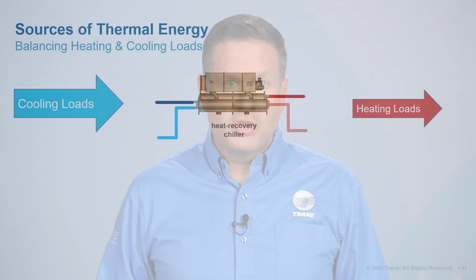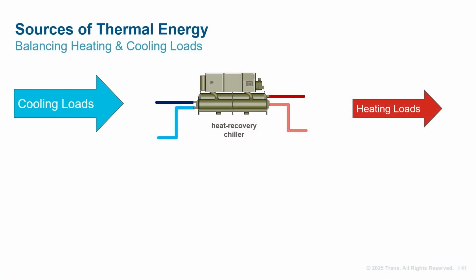When heat recovery is used, the waste heat from chilled water loads is used as a source of heat for heating loads. This is an optimal arrangement as long as the system is cooling dominant. Cooling dominant systems have an overall surplus of heat. Any heat that's not used for heating loads must be rejected to a cooling tower or another heat sink.